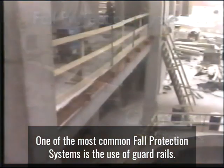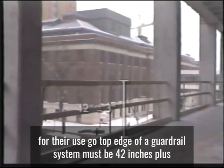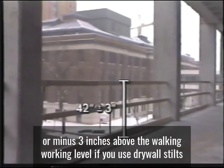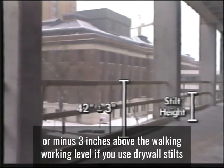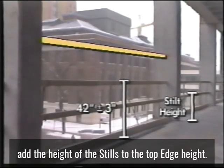One of the most common fall protection systems is the use of guardrails. Here are some requirements for their use. The top edge of a guardrail system must be 42 inches, plus or minus 3 inches, above the walking working level. If you use drywall stilts, add the height of the stilts to the top edge height.